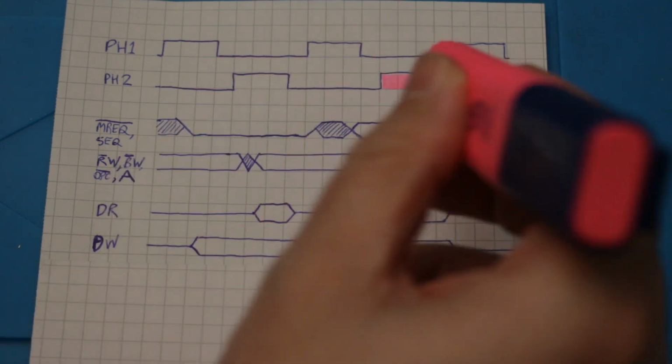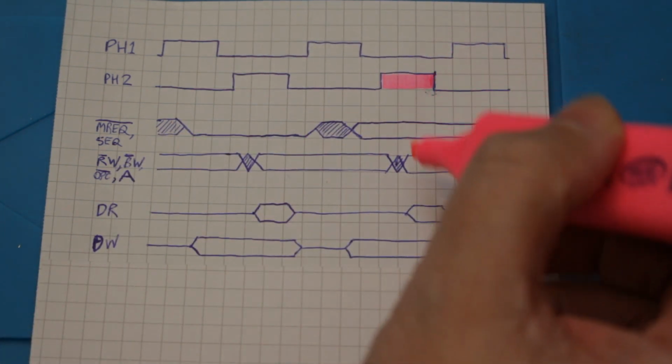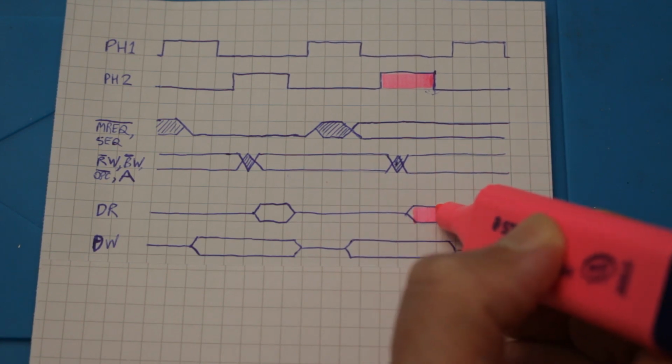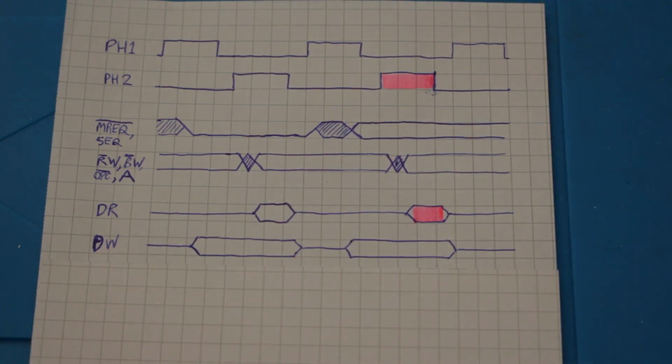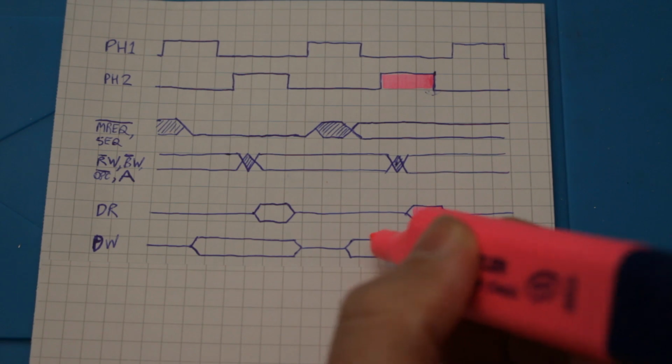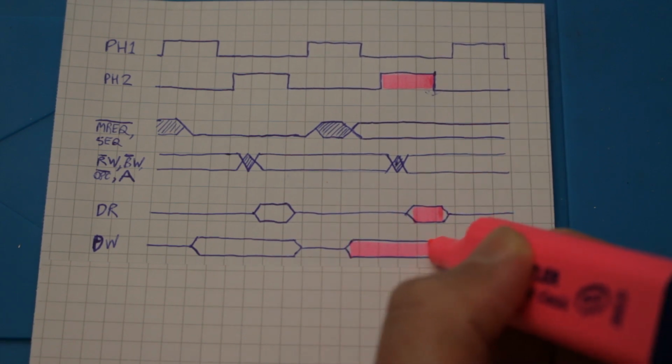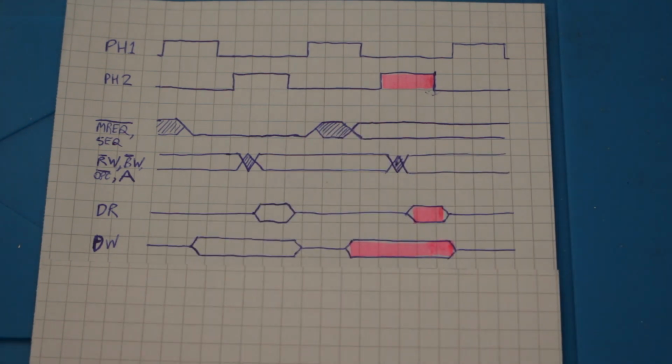And during this second cycle, if it was a read cycle, then this block of time would be relevant for the read. That's the block of time that shows when we need to make sure that the memory is outputting to the data bus so that the CPU can read from it. And if it was a write cycle, then this block at the bottom would be the relevant block for the data bus access. And that means that the CPU would be presenting data for us to write to memory during that period.